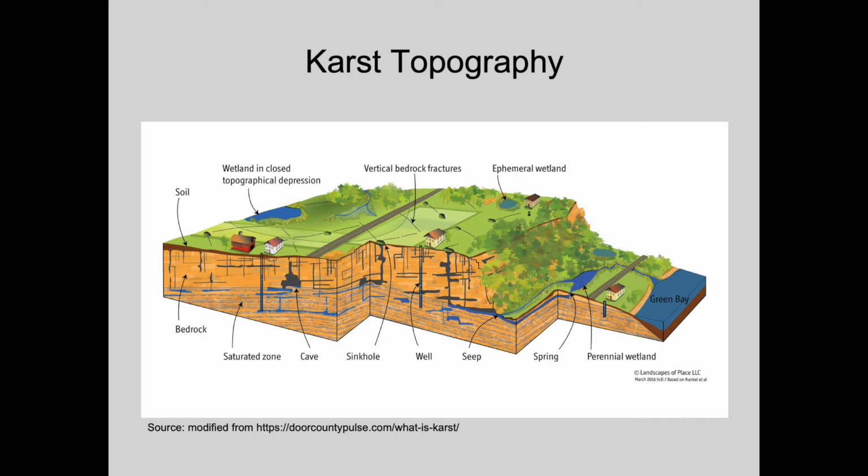So let me restate that again. There is a third characteristic that's important. We need a nicely defined zone of aeration, or we need strata within this region, within the profile of a developing karst environment, that will be air containing. It will allow water to move down from the surface as it approaches the groundwater table, and it will also allow that water to begin the process of chemical weathering as it interacts with the soil and then eventually the regolith that is part of this eventual subsurface landscape.